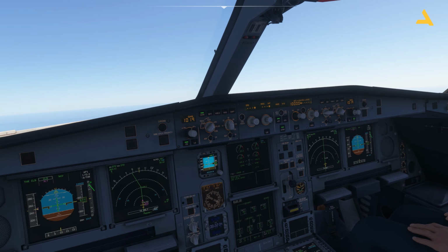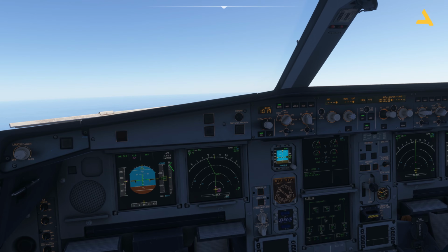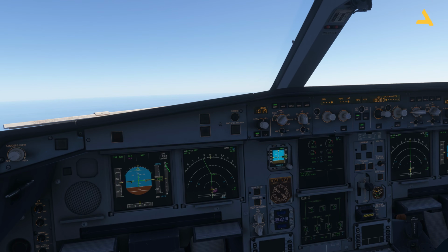Now there is also another option, vertical speed. Right now you can see that the plane is giving priority to the speed. It's locking the speed, but it's changing the vertical speed. So the climb rate keeps on changing throughout the flight. As the plane goes up, the air gets thinner, so you cannot have a very high vertical speed. It has to be reduced. But you can take control of the vertical speed. If you look at this knob, you bring your cursor over here and you press it. Now you have the control for the vertical speed.